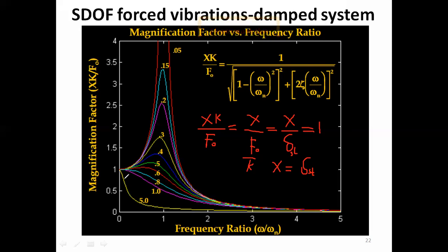So you could see the response of the overdamped system. Here, when the frequency ratio is very near to 0, it would have a value which is equal to the static deflection. Afterward, at higher values of frequency ratios, the amplitude of vibration would be very, very less.